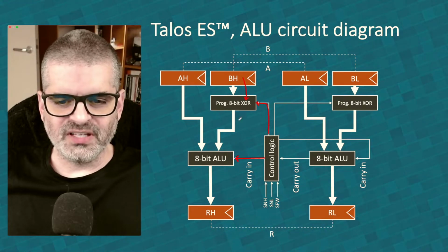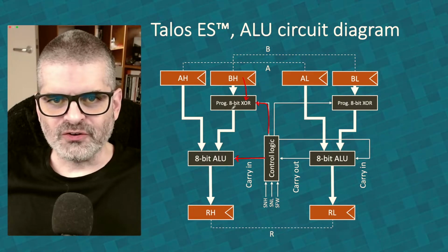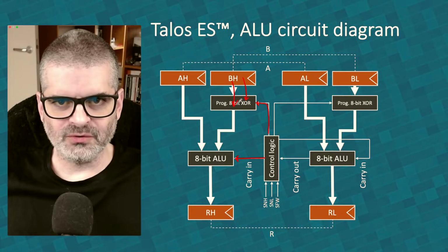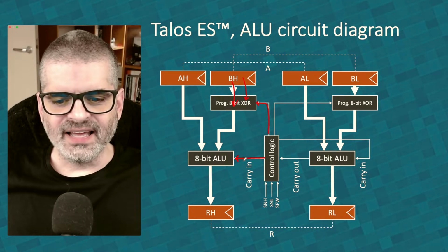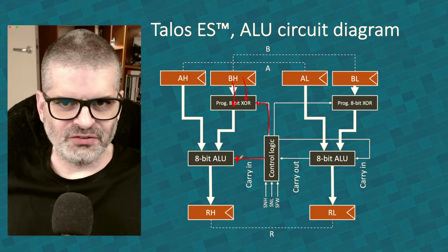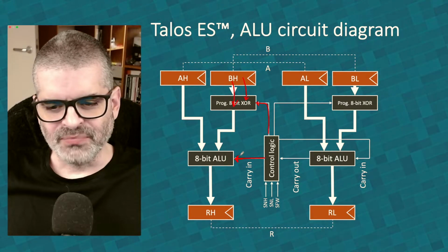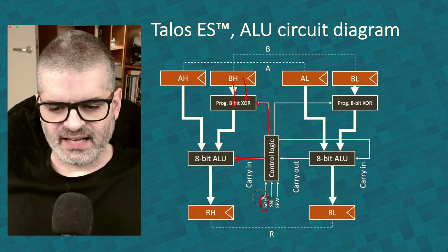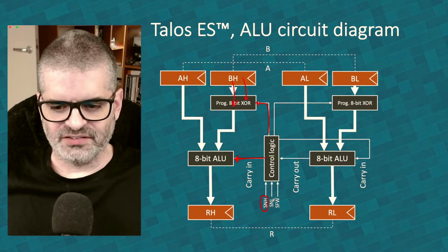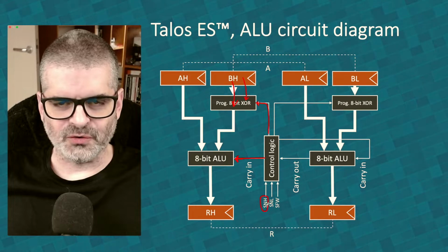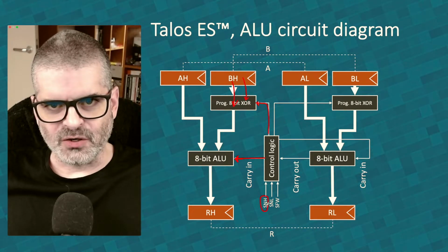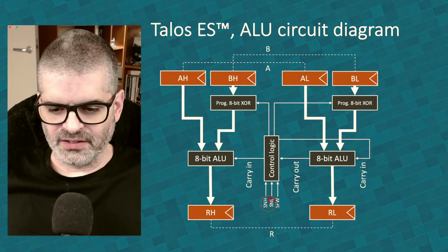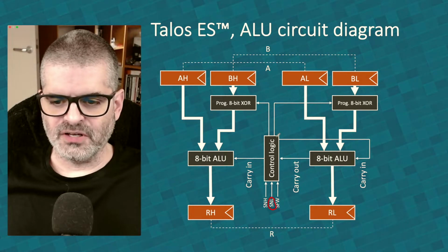And that's exactly what we need to create a full 2's complement operation. We need to invert the contents of one of the operands, which becomes the subtrahend, and add 1 to it, which is the same as to add 1 to the result. So that's what happens when you set negative for the high part, set negative high. Again, this is a control bit that comes from the decoded instruction word. Now the same thing applies for the other side, set negative low.